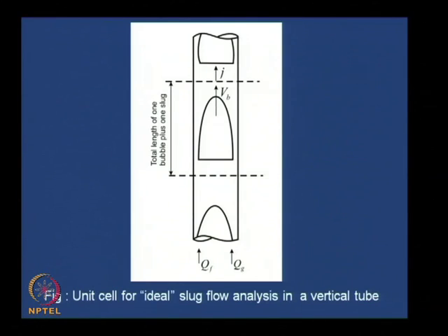So, under that condition we find that the flow patterns are independent of inclination, and there is not much difference in the flow distribution in a horizontal as well as a vertical tube. We find in both there is no stratification for micro channels, say 1 millimeter, 2 millimeter channels. We usually get slug and annular flow patterns predominantly in both cases. Okay. So, under that condition it is different, otherwise the analysis for vertical slug flow cannot be extended in a straightforward manner for horizontal slug flow. So, to start with, we start the analysis for vertical slug flow.